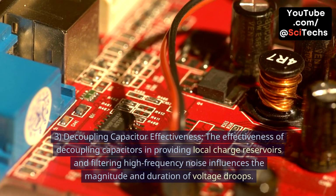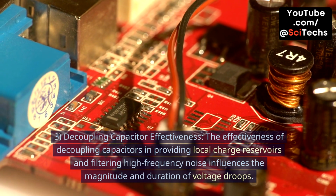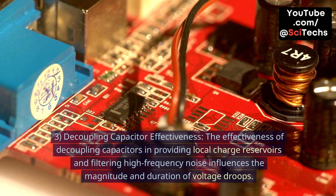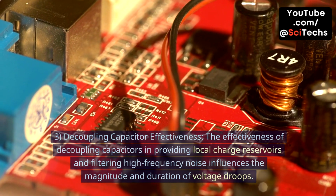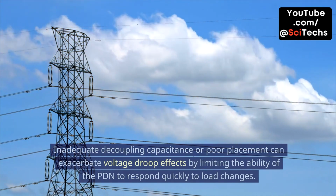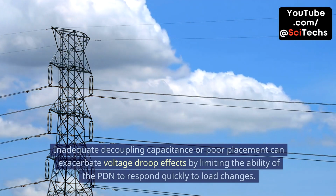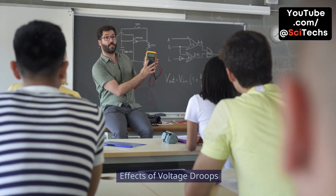3. Decoupling capacitor effectiveness. The effectiveness of decoupling capacitors in providing local charge reservoirs and filtering high-frequency noise influences the magnitude and duration of voltage droops. Inadequate decoupling capacitance or poor placement can exacerbate voltage droop effects by limiting the ability of the PDN to respond quickly to load changes. Effects of voltage droops.